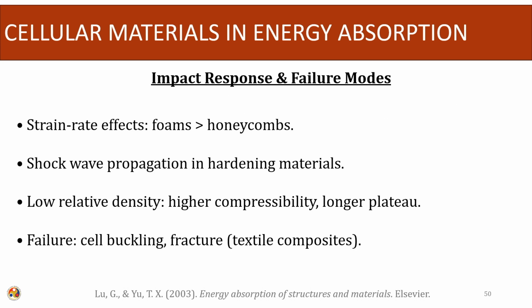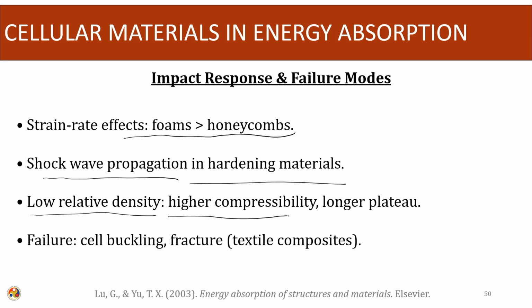So, what are the different impact responses and the failure modes? The strain rate effects are there. Shock wave propagation results in hardening of the material. It has a low relative density, so owing to the low relative density, the compressibility is very high. And it has a longer plateau, and normally the failure mode occurs by cell buckling or fracture of the composites. Either the cell is going to buckle or fracture will occur in the material.